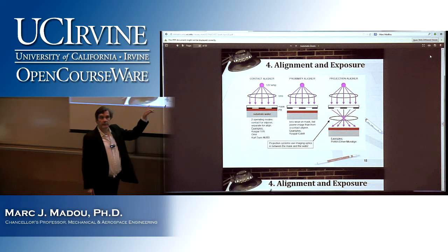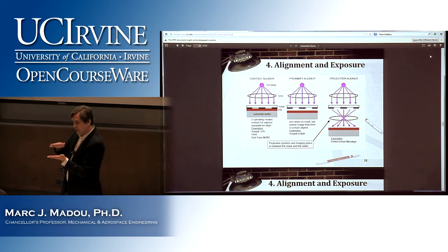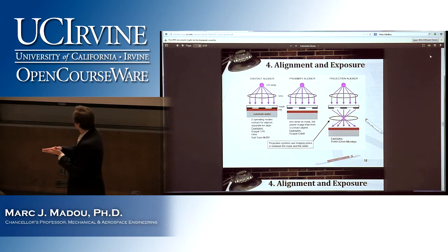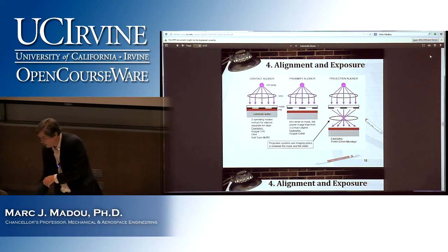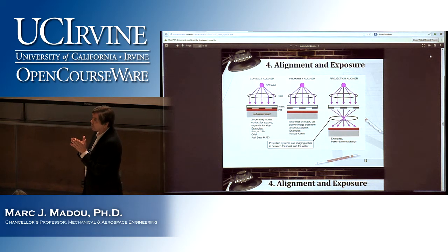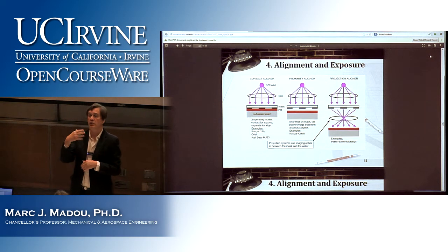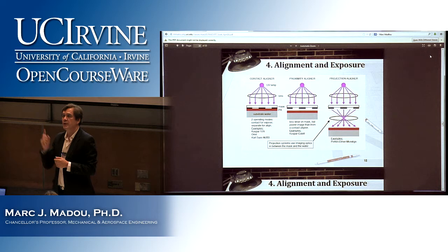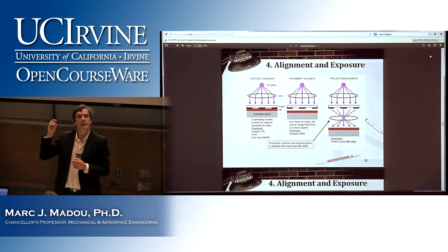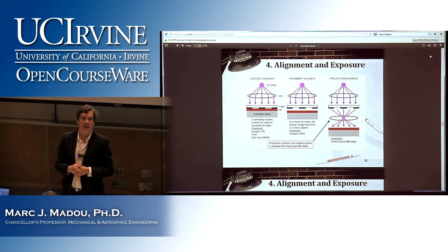These three pictures sketch the different relations you can have between your mask and your silicon wafer. On the left, you basically have your mask sitting on the wafer. In the middle picture, you have a small gap between the two called proximity printing. On the right, there's a lens between them. Now, when we talk about this resolution equation and depth of focus, to which one of these three does that apply? Projection only, because if there's no lens, you don't have a numerical aperture.